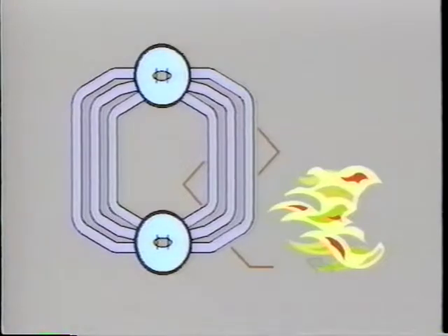Gases of combustion are directed by baffles around the tubes. Water in the tubes is heated and rises to the steam and water drum where steam is released. Cooler water descends through downcomers to the mud drum.